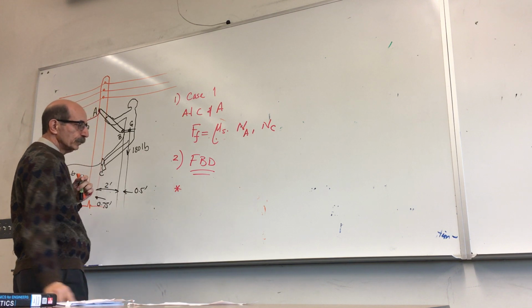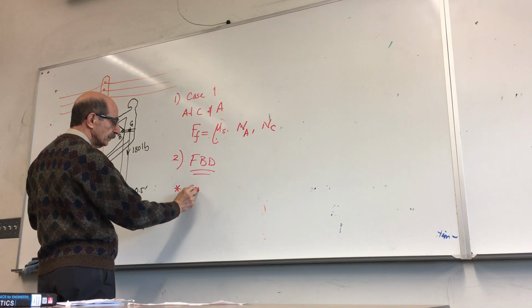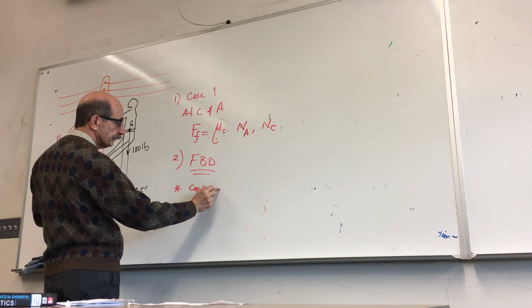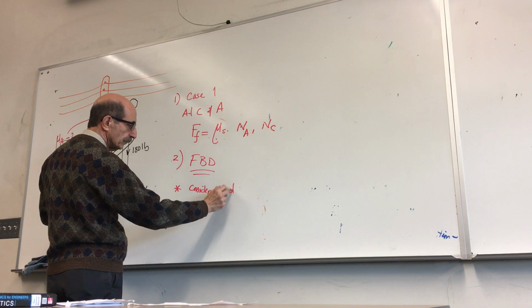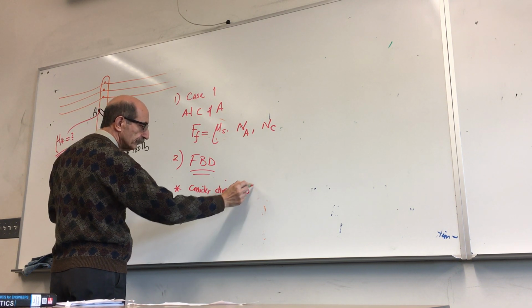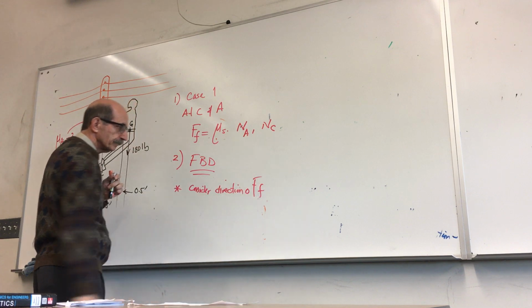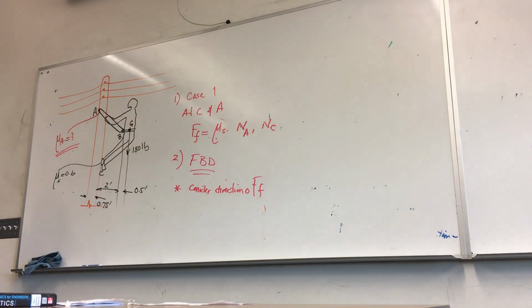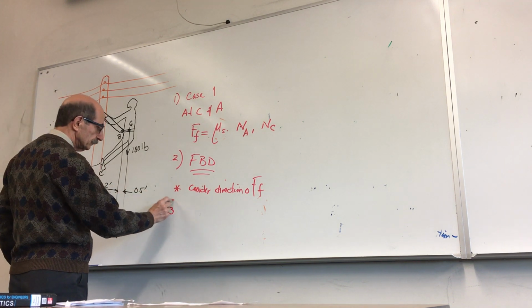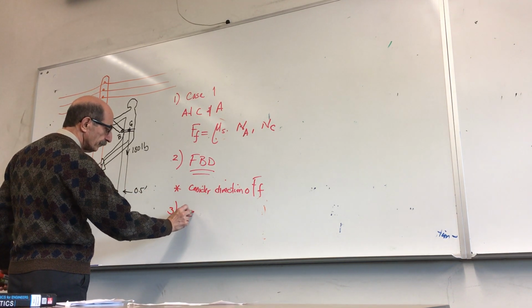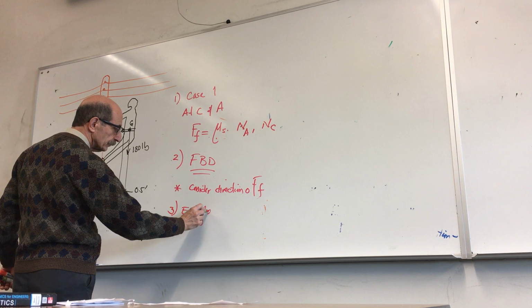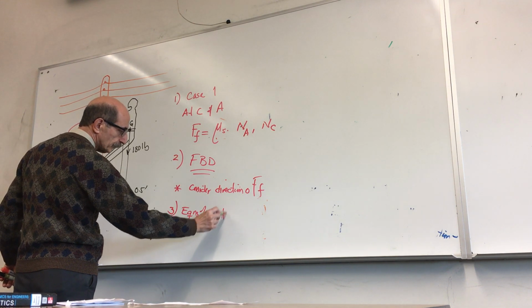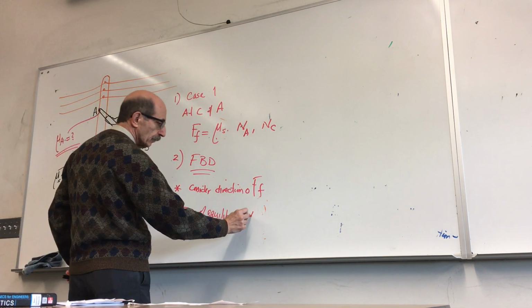And I would put here, consider the direction of the force of friction. And then apply equations of equilibrium. Find only the unknowns that you need to find, with equations of equilibrium that will give you the unknowns.